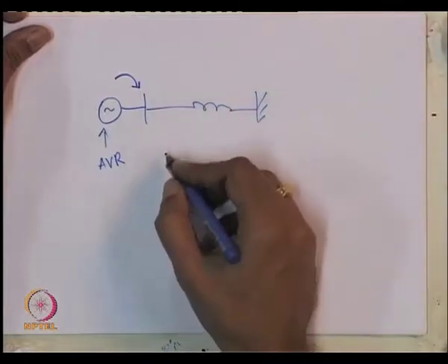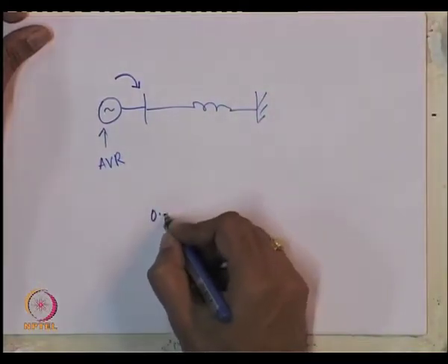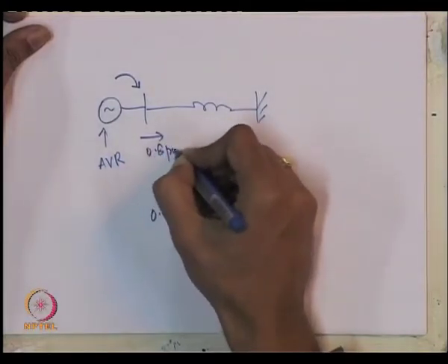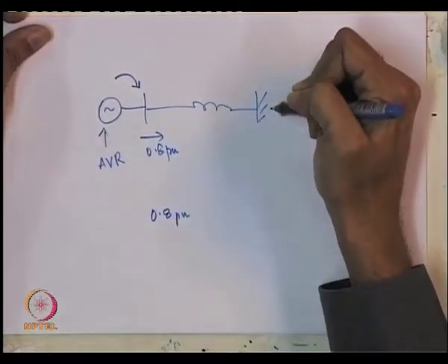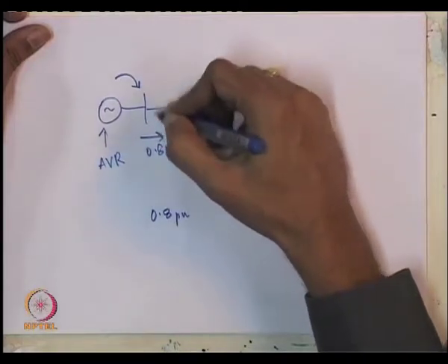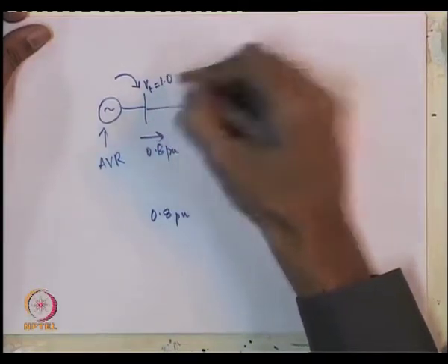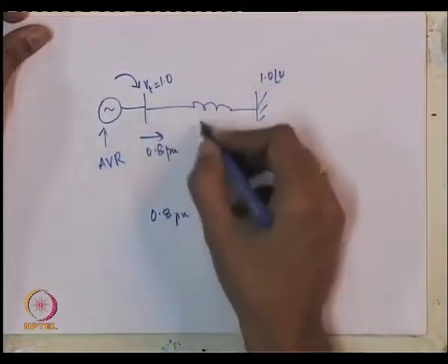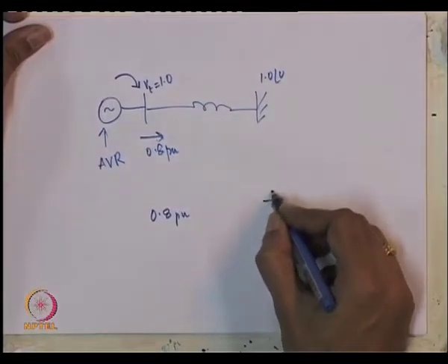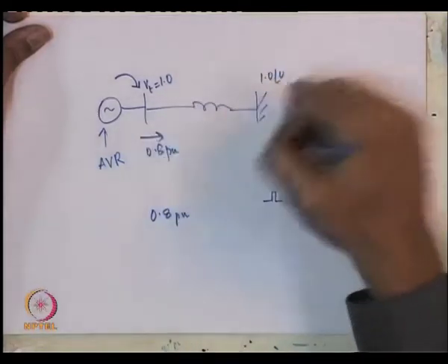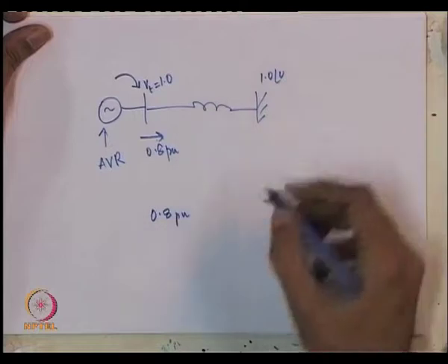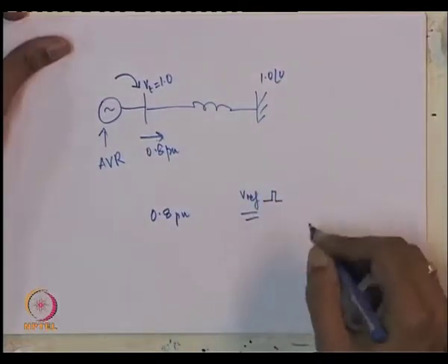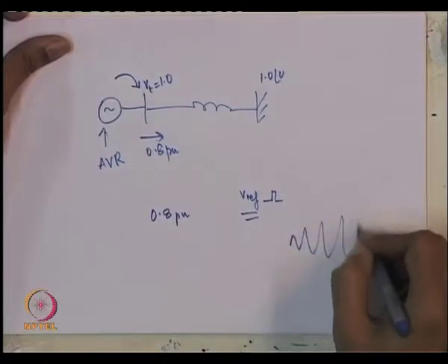We saw that for certain operating points, like 0.8 per unit power output of the generator and terminal voltage magnitude of 1, for a small disturbance around an equilibrium corresponding to this scenario, a small pulse change in Vref of the AVR excited an oscillation which grew with time.